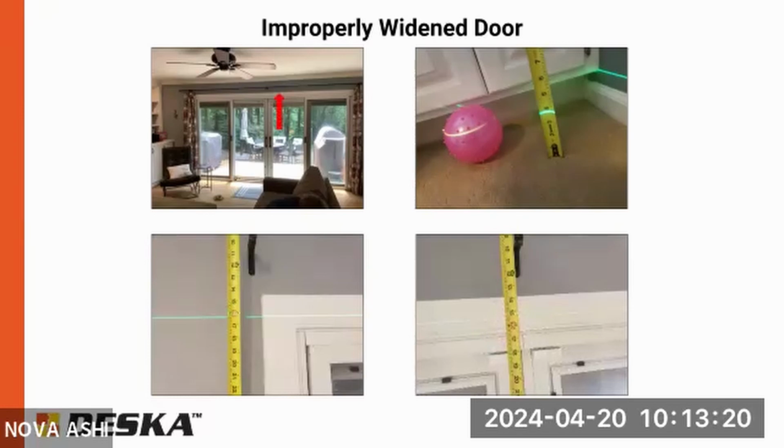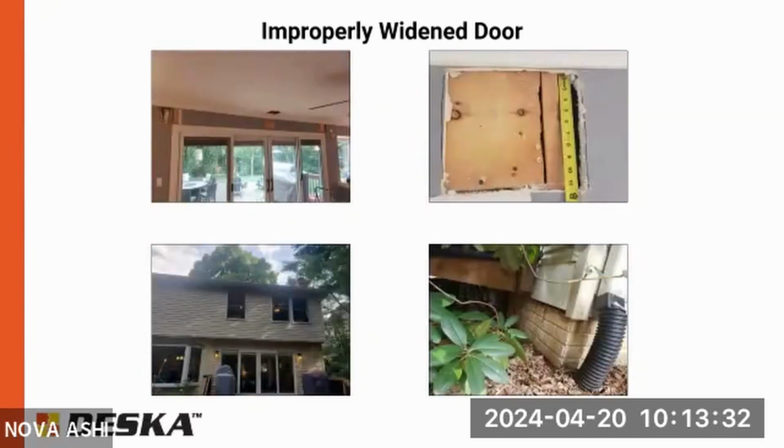And then we had him remove a little bit of drywall. Here you can see the difference with the laser between the ends versus the center. Similar to the garage issue, it was a double, in this case, 2x12. This one was supporting even less, but still this double 2x12 was rated for about 300 pounds per linear foot. The service load, the actual load of what's there, dead load plus live load, should have been rated for 1,100 pounds per linear foot.